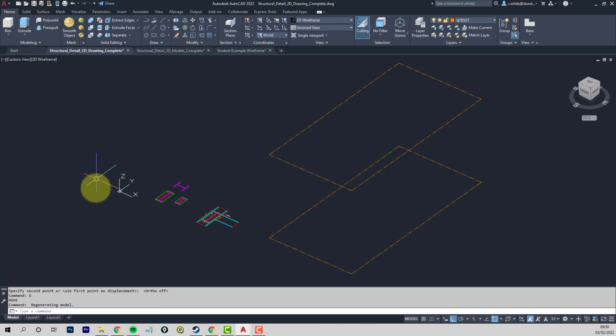In Rhino, which is another 3D package that we use a lot, it's called construction planes, but it's exactly the same. We can manipulate this by rotating about whichever axis we want. We'd have to know the angles we want to move to do that, or you can use this drop down list to give you the standard orthogonal directions.